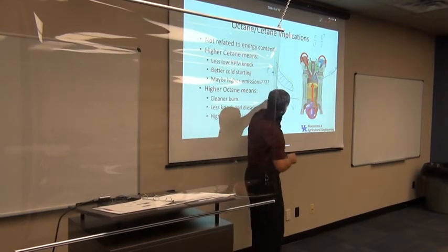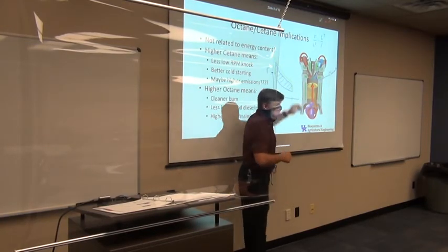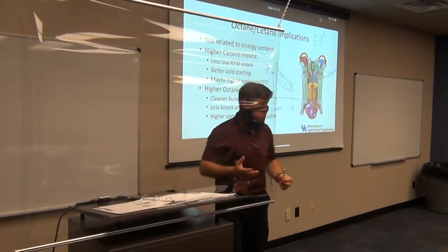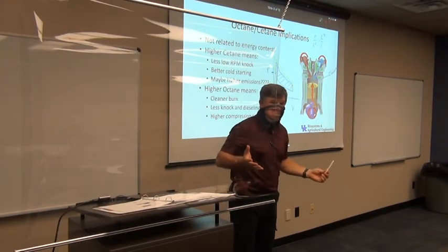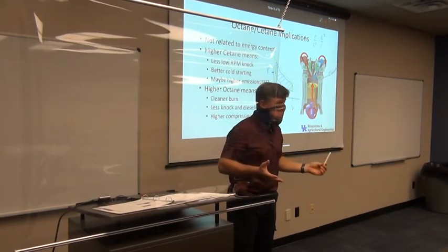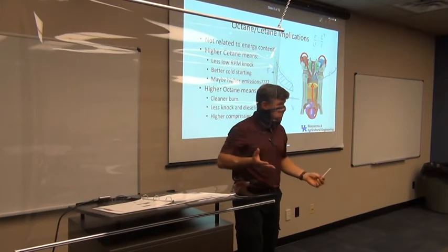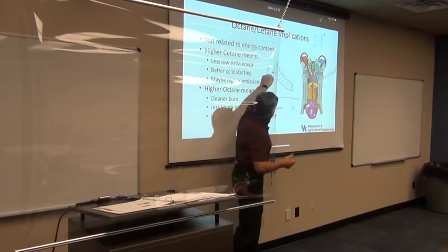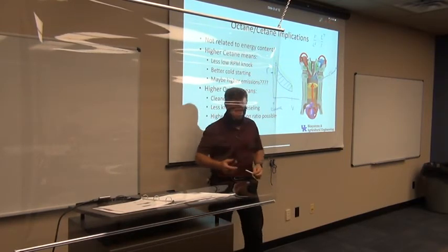In my original engine, moving that auto ignition pressure up without any modification, would it have changed the power output? Does it change that PV curve? No. How do I get more power out of high octane fuel? I've got to have the compression ratio to make that happen.